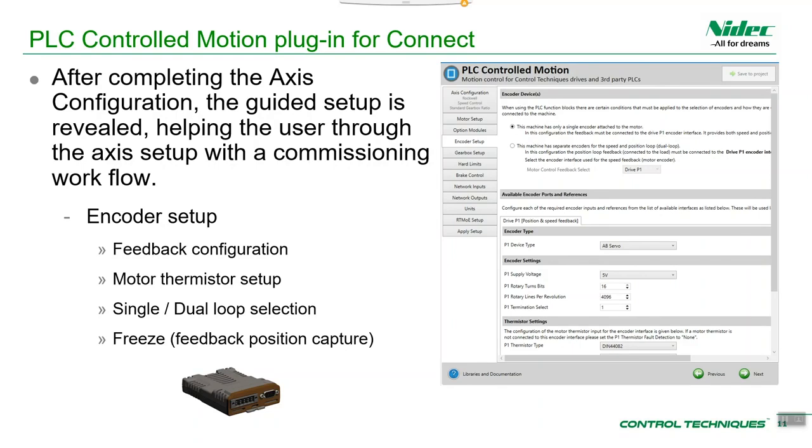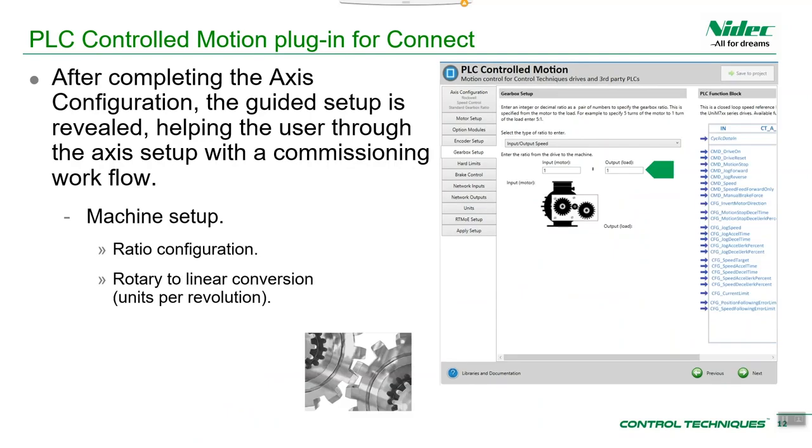Okay, so this is for the AMC motion control type motion interfaces. You don't have this kind of setup for RPM type axis or frequency control type axis. Other things that you've got under here are things like freeze position capture. So if you want to know with a high precision the position of the axis, so you're doing like a custom homing routine or something like that, you've got that capability here, and the configuration for that is in this tab.